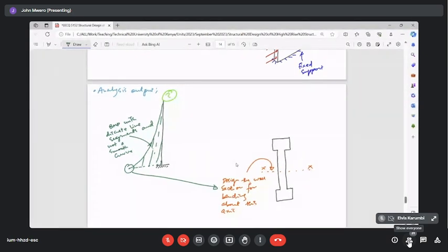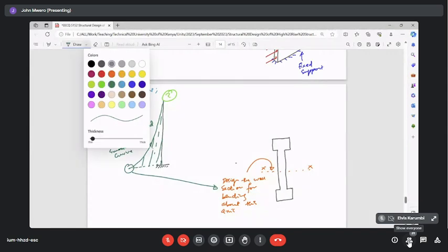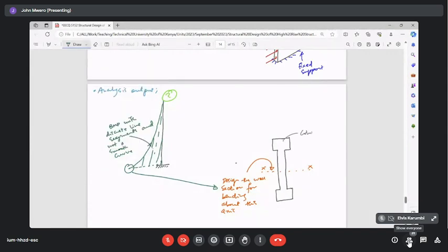Okay, and maybe just so that we will remember, that would be a column that is fused with the wall, and that is the wall itself. Now, there exist several approaches to how a shear wall can be designed. Some schools of thought take the entire wall section as one element in bending and find the reinforcement for that and distribute it throughout the whole wall.